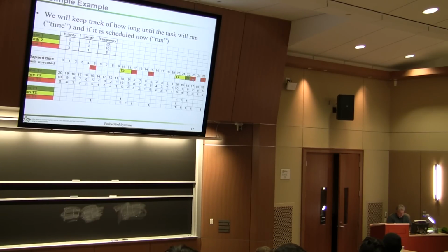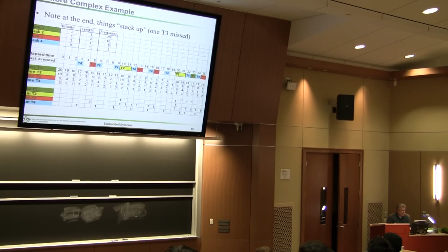If it needs to be run immediately, then it needs to be what's called a hard real-time task. So this is lightly loaded. Let's take a look at this next example. We've now added another task. Task number 4 with 0 priority, which means it has the highest priority. And look at this, it runs really often. So in this case, again, we count down 3, 2, 1, 3, 2, 1, 3, 2, 1.